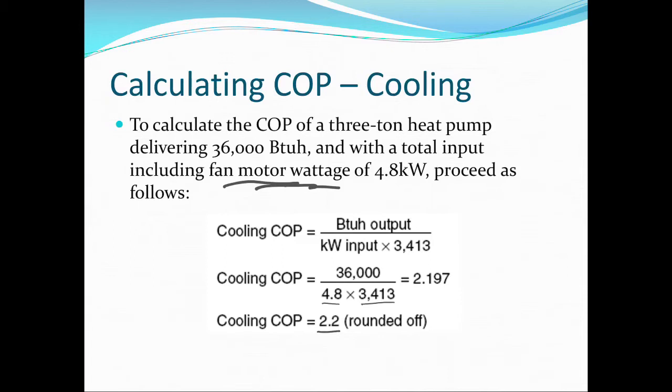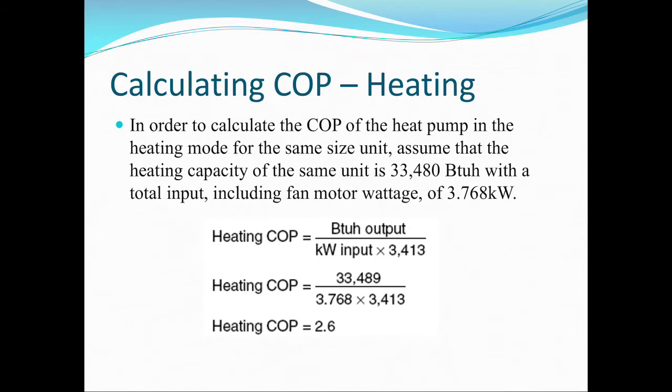But like I said, usually that's not something that we normally look at in cooling. It's more for heating. So in heating, the big thing is really that the coefficient of performance has to be compared: is it worth it for me to run this heat pump compared to the alternative fuel source or the alternative system?